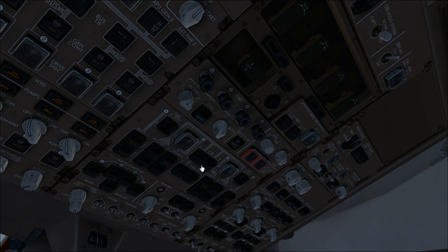Fuel panel, crossfeed valve switches set on. Check the valve lights go out in a few seconds, and you can check everything is fine. In case you receive a fuel tank to engine indication in yellow on the upper DU, this means you have to change the selection of the fuel panel.